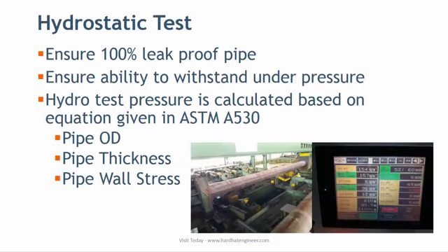Pressure is monitored by computerized system. For welded pipe, the test pressure should be held for the time sufficient to permit the inspector to examine the entire length of the weld seam. Hydro test can be waived under certain conditions as set out in the standard.